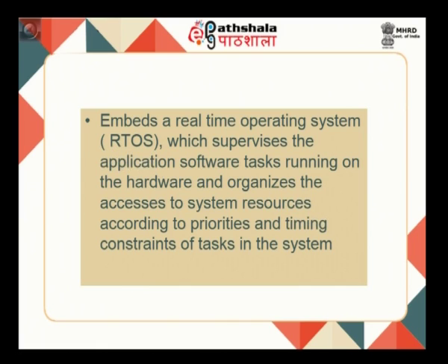Now just look at over there, we have discussed embedded system and embedded system architecture, and we have gone through it. In that we will be having hardware, we will be having software. Your software is embedded onto your hardware and the whole overall process is monitored by your operating system, that too through your real time operating system, and this real time operating system works based on priority. That means, dynamic priority or static priority will be assigned during the application while it runs this particular process.